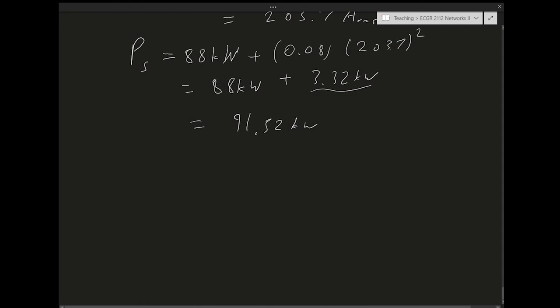And for that improvement, nothing happened. The utility did not improve the transmission line. It did not go out and change the transmission line to one that has less resistance. That's too expensive. What happened is just that the power factor was improved at the load. Okay, so power factor has an economic impact. That's why it's a factor that's very prominent in studying power systems.